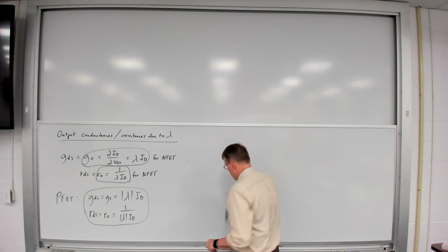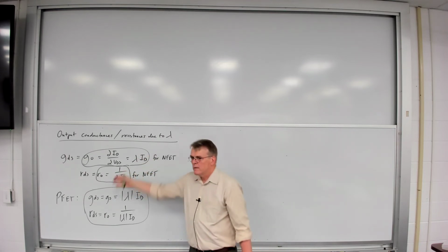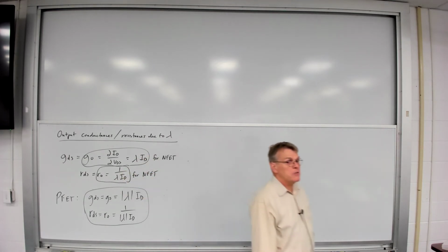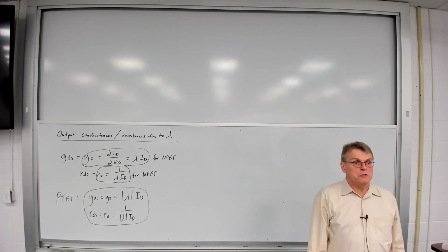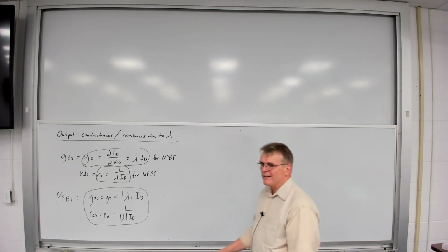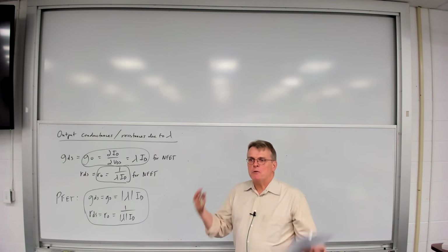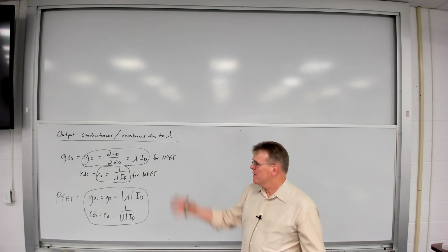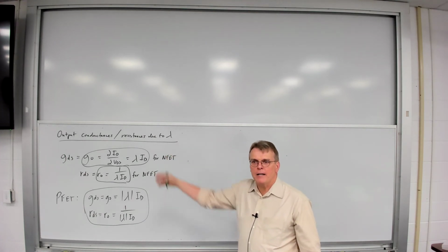Now, I mentioned before, saturation is actually a desirable operating region for MOSFETs. In fact, amplifiers are almost exclusively designed using MOSFETs operating in saturation.